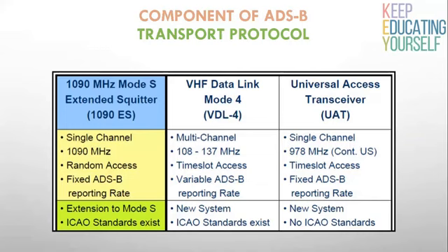VDL Mode 4. The VDL Mode 4 system could utilize one or more of the existing aeronautical VHF frequencies as the radio frequency physical layer for ADS-B transmissions. It is best used for short message transmissions between a large number of users. VDL4 uses a protocol that allows it to be self-organizing, meaning no master ground station is required. In November 2001, this protocol was published by the International Civil Aviation Organization (ICAO) as a global standard.